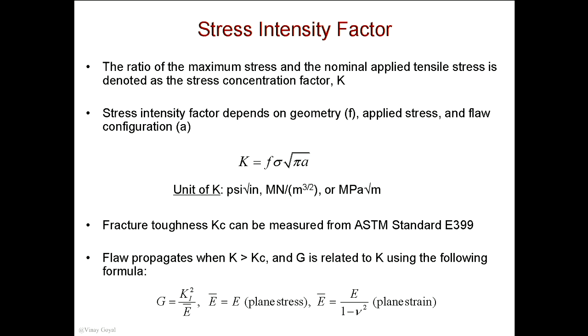And so K usually takes this form. K is equal to F times sigma times square root of pi times a. F is typically geometry and loading dependent. Sigma is usually the far field stress. Pi, you guys know what pi is, hopefully.